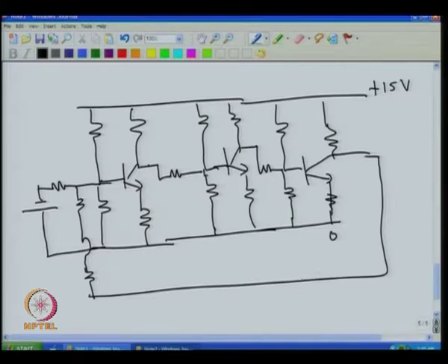Eventually what will happen is, if I stabilize the loop by putting capacitors and so on, you will see this one is getting contribution from this as well as from this, the two contributors: one from this feedback voltage, another from the applied voltage. This one tries to go close to 0, that is what happens, because when this is just about 0.6 or so, it conducts, and then it gets some voltage, so that this also gets some amplified voltage, and this also gets the amplified voltage that comes from here.